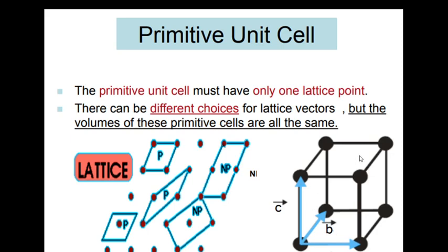Let us say, if you keep the same analogy, 4 on top, 4 on bottom and 1 atom is, let us assume, in the center. So this cube will become body centered. In this body centered cell, you think that 8 corner atoms or lattice points are available. So 8 multiplied by 1/8 becomes 1, and 1 is in the center, so it becomes 1 plus 1. So it carries 2 atoms if it is the case of the body center.